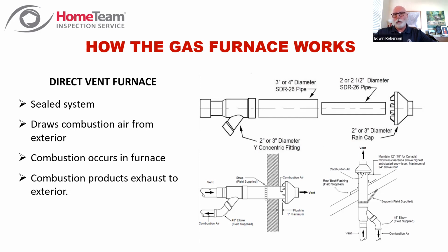In the business they're in, they should know better than to seal that space without advising, hey, you need to do something about this HVAC. Conversely, when the HVAC guys came in to replace that furnace, the crawl space was already sealed, and they turned around and replaced the furnace with another like in kind that needed to draw air from the space. So that was a case where both contractors dropped the ball.